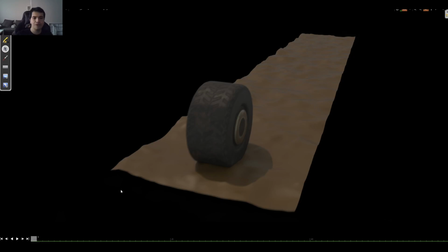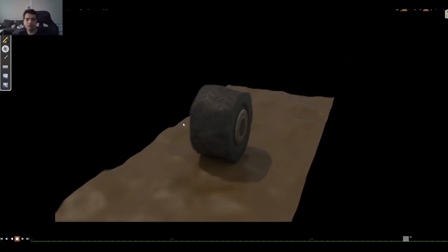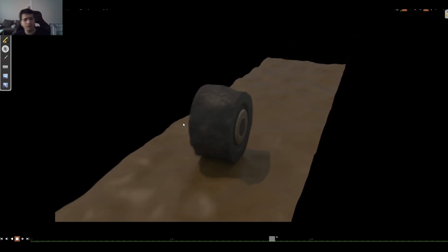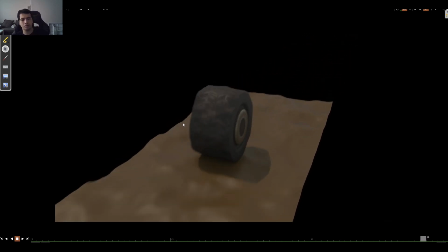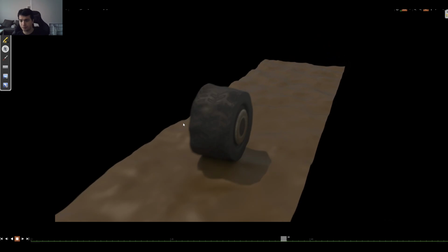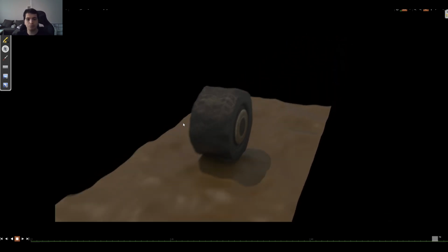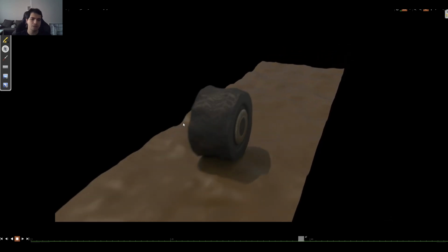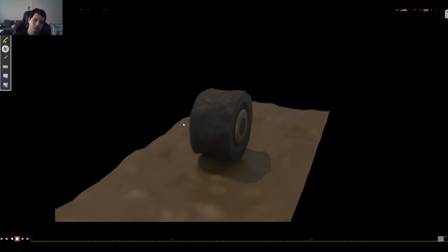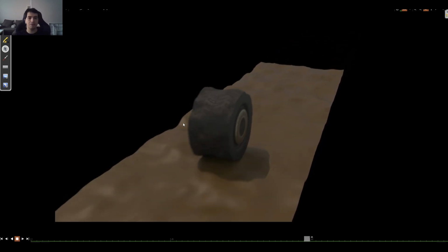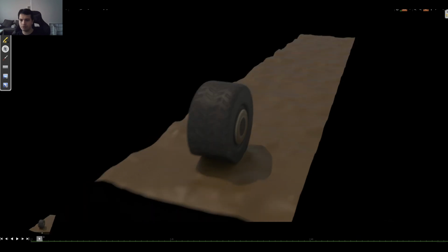Hello everyone, today we will be creating a simple mesh deformer using SOP solver and wrangles. I want this to be a VEX exercise, so we will use intersect functions inside VEX rather than RAY SOP. And also I will give you some small tips and tricks about preserving your UVs while creating high-res meshes from low-res geometry. Now this is a low-res geoform that I found in Sketchfab. I will put the link down below so you can download it from there as well.